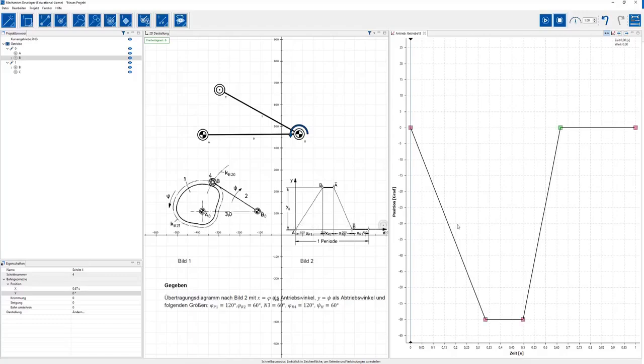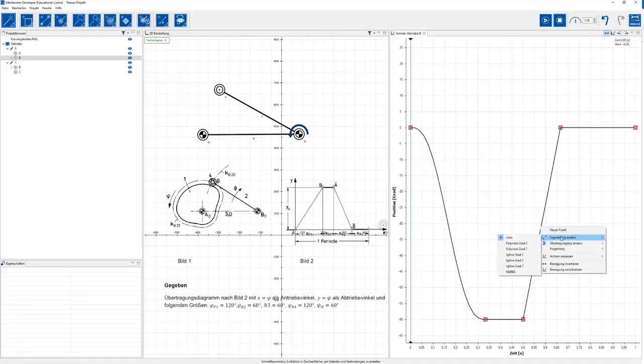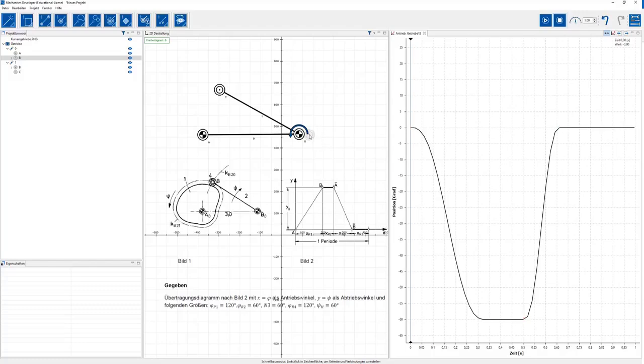Next I want to apply motion laws. I choose a 5th-degree polynomial, which is specified here. And I also select a segment type of 5th-degree polynomial. These are now my motion definitions. We know that a cam mechanism operates between these elements. Here there's a quick construction mode for the cam mechanisms, which I can use to generate one. I simply click on the first joint and then on the second joint, and the cam profile appears.